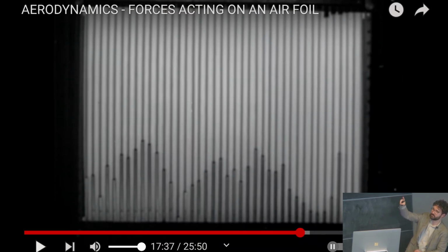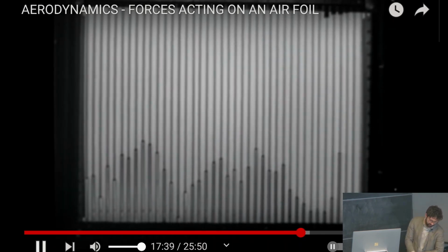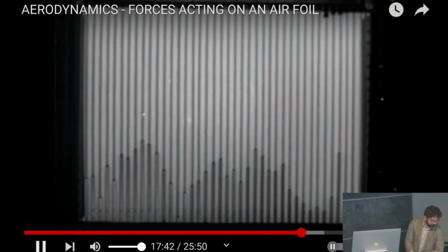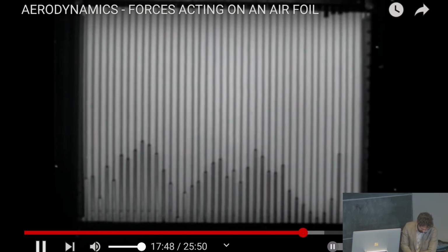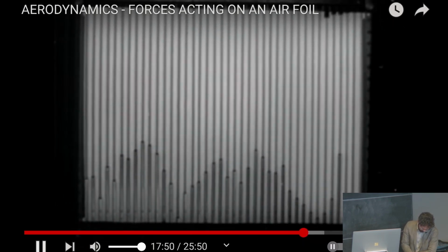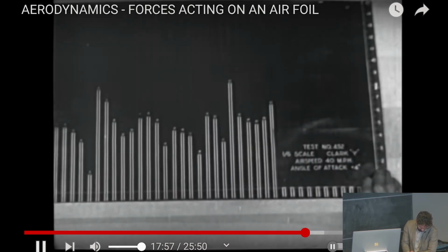If you know where each of the tubes goes to, then you can calculate pressure distributions by measuring the manometer. Levels fluctuate slightly as minute variations in airspeed or density occur, but the ratios are constant, and the position of the liquid in the tube shows both positive and negative values for the airfoil.